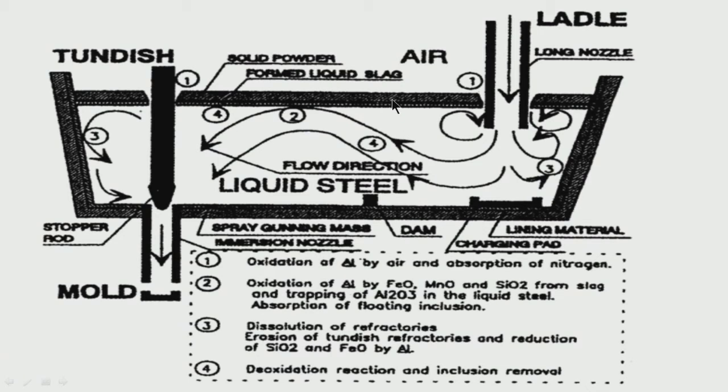The bottom slag which is just at the top of the liquid steel is basically a basic slag. On top of that we use rice husk, which is a good insulation material. This does not allow the liquid steel temperature to come down. So, we have a 2-stage slag.